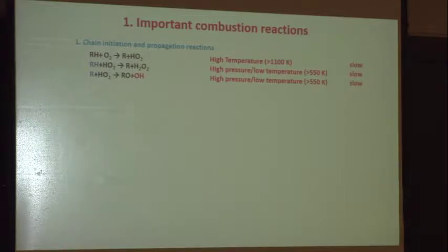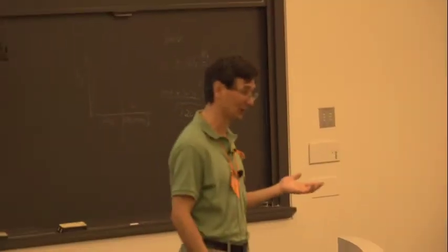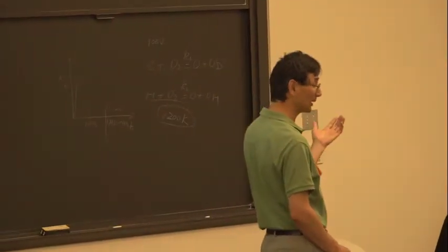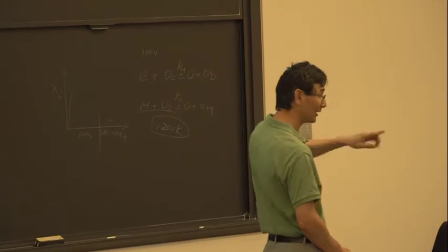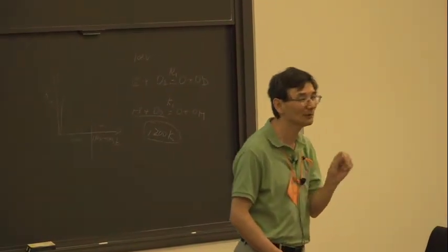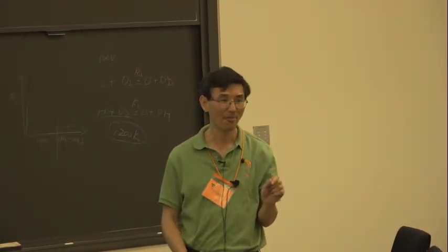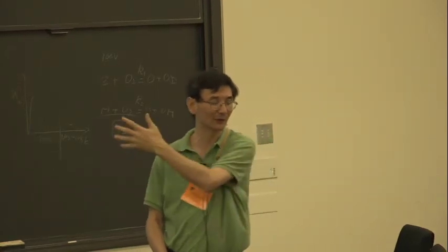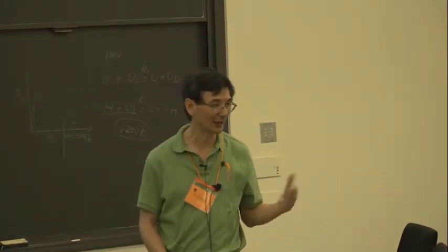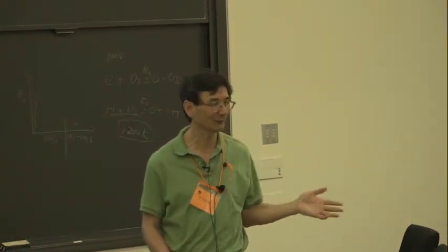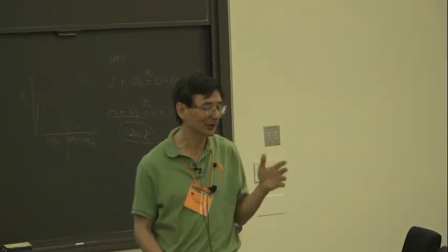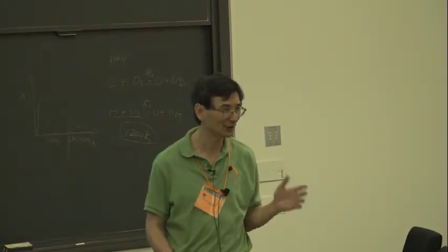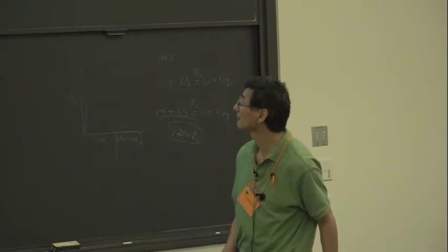If the problem is limited by chain initiation reactions, then you find, oh, I have an opportunity: using plasma to generate initial radicals and set everything going. That is one key thing in scramjet engines. In a scramjet, the flow is air with hydrogen, and the hydrogen does not have radicals to go, and you need some radicals to initiate the chain branching reaction. Then you need plasma to do that.